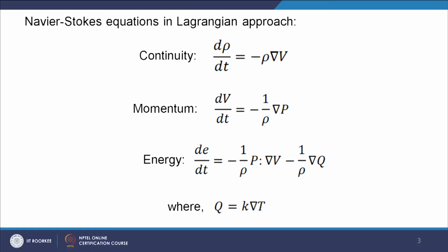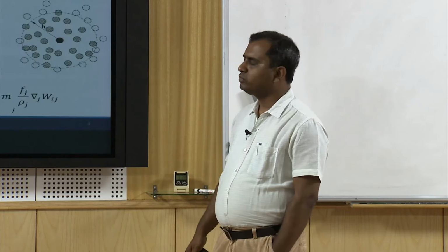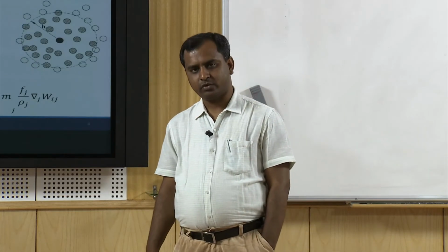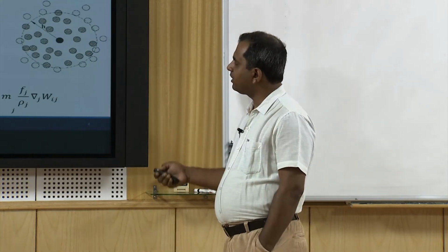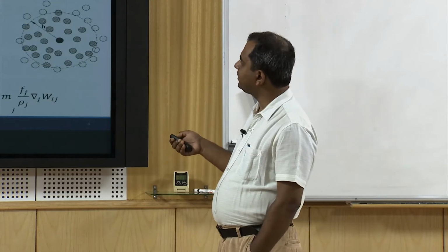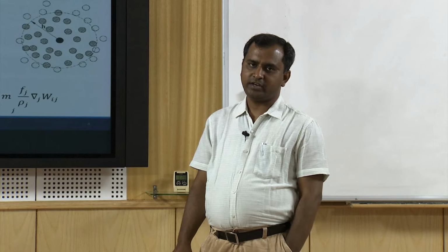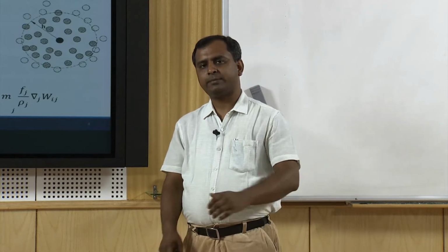These equations come from fluid mechanics, so I am not going to elaborate on them. Let us see how, using smoothed particle hydrodynamics, we can tackle this type of equation, especially for two-phase flow. In smoothed particle hydrodynamics the domain is discretized using Lagrangian particles. This is a new concept in our common computational fluid dynamics analysis.